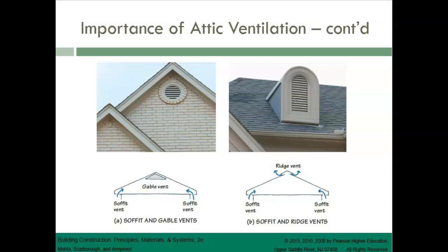There are 2 main options for attic ventilation. One would be the use of gable vents, and the other would be the use of ridge vents. In both cases, air is entered through the soffit vents and it exits through the vents at the roof.